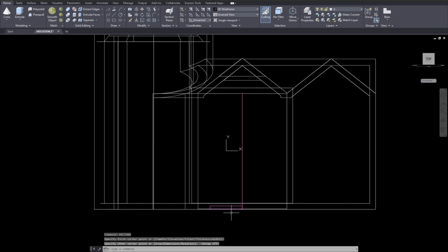Okay. Now I'm going to create another rectangle from where it is finished. And I'm using object snap this time. And this time it's going to be the width of the door. Okay, the door is 3 feet wide, so this is going to be 1.5.